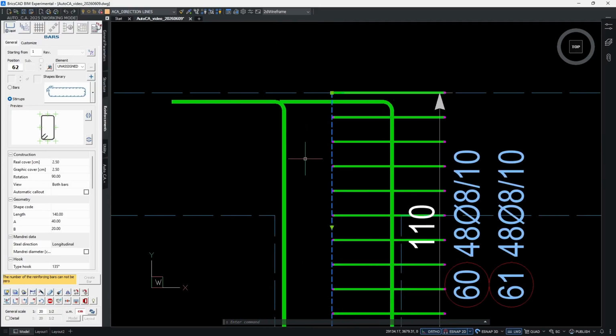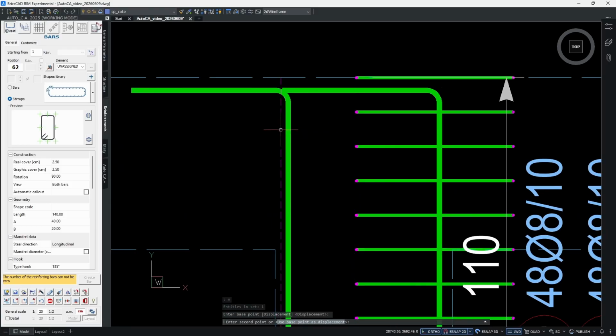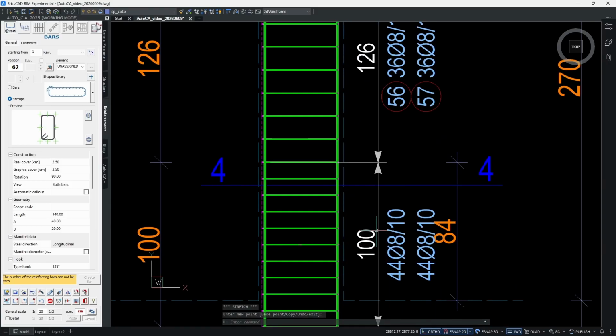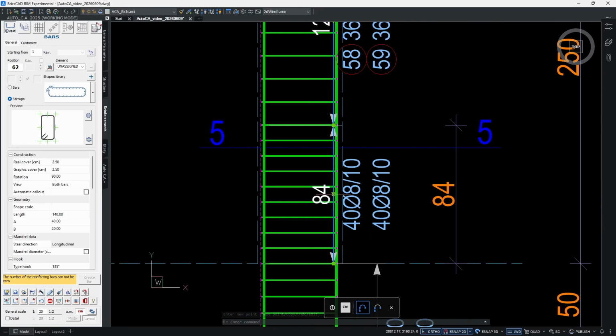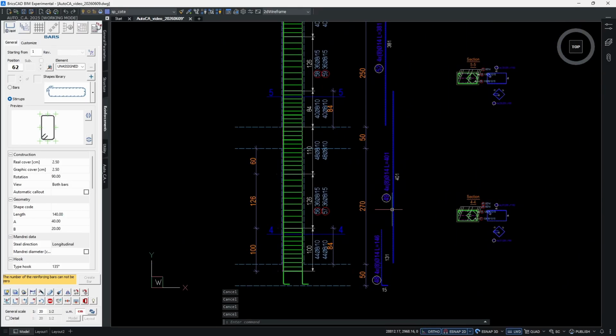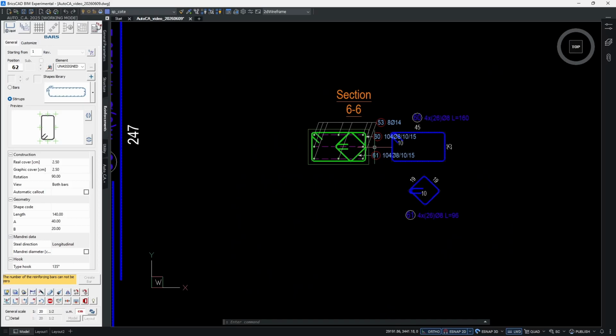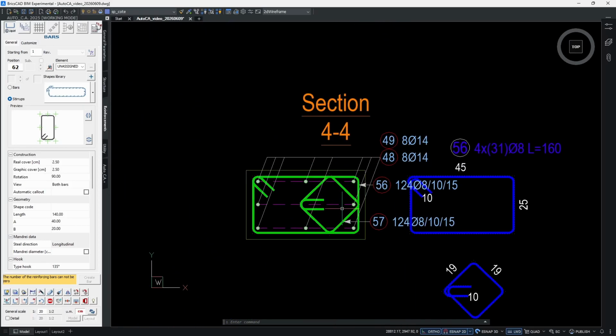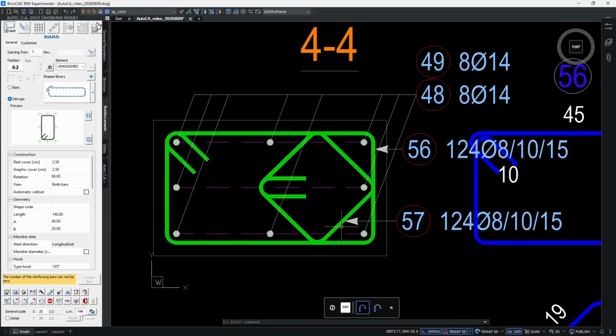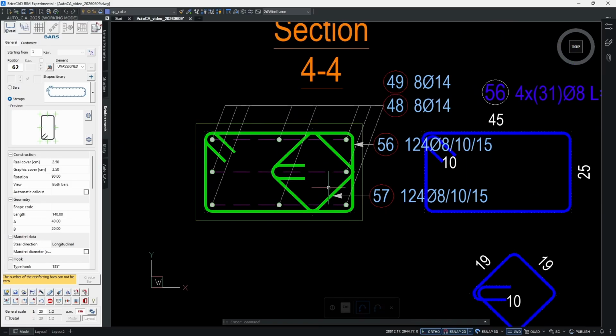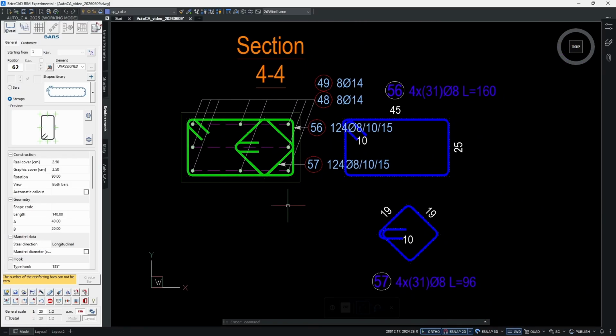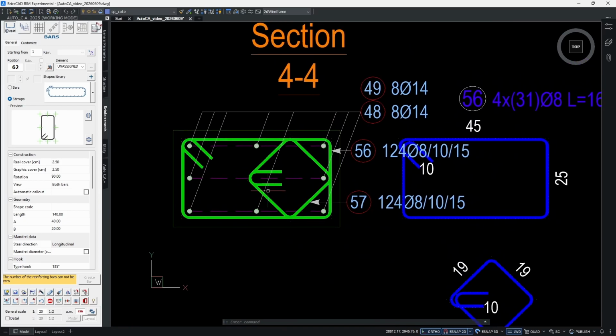We just need to put the distribution back to its place. Okay, all right. Relocate callouts. You can see them easily. Nice. And now we need to think about the inner stirrup, because now we don't need the rhombus shape. We just need another rectangle inside the bigger rectangle.